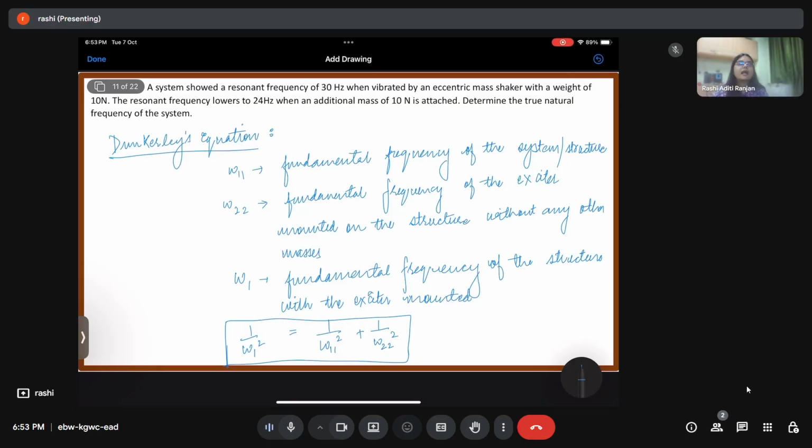But in a practical situation, we have every kind of damping: damping because of air resistance, structural damping, and different factors that contribute towards the decrement of the energy of the system. So using any one kind of behavior is not going to give us the correct estimation of the fundamental frequency. So it is better that we excite the system.